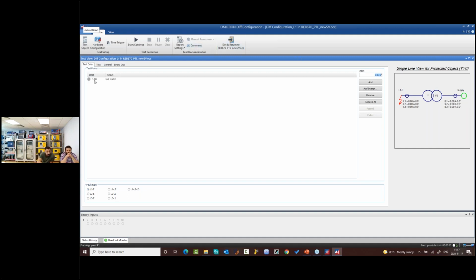Here I need to test at 1 I bias to confirm that my system is stable. Once I need that, I can press continue. Then no trip will come from the relay. Then I'm injecting, and as you can see, this green means it is synchronized to the PTP switch, so everything is fine. If you are using one single CMC, you don't need this. Now, since there is no trip from the relay, I can just press pass.